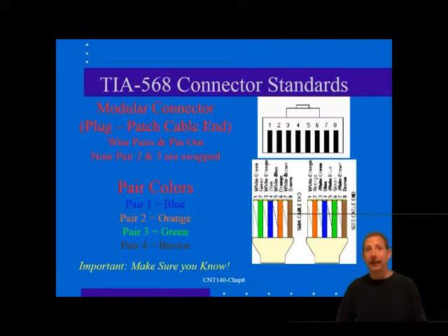Technically, you can use either pattern. However, some patch or fan-out cables, equipment connectors, and adapters are pre-wired with the 568B pattern, and you must match that pattern at the other end of the cable if you want it to work. You can, however, mix patterns from one cable run to the next within the same link. For example, a patch cord could be wired with either pattern without regard to how the horizontal cable is terminated.